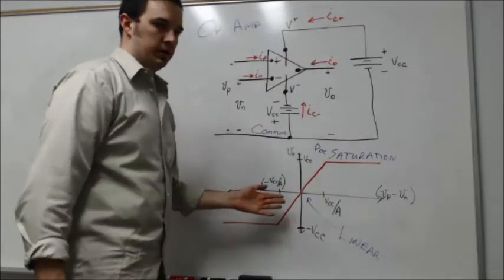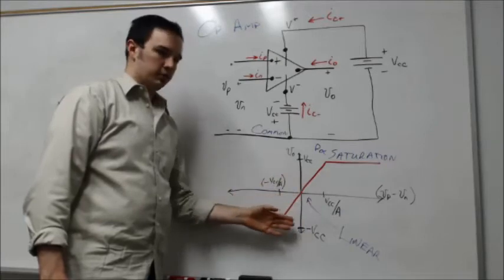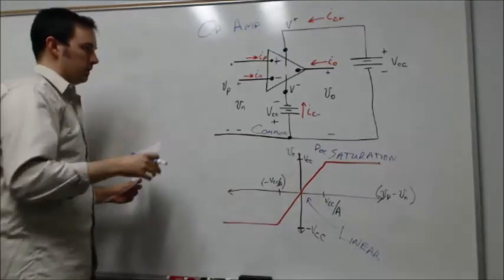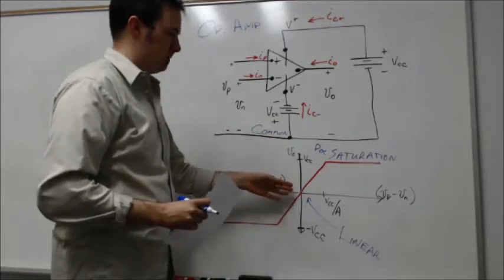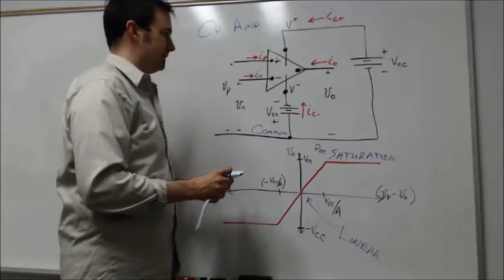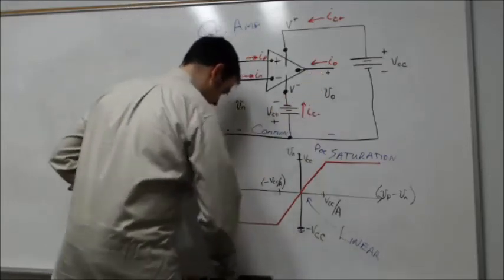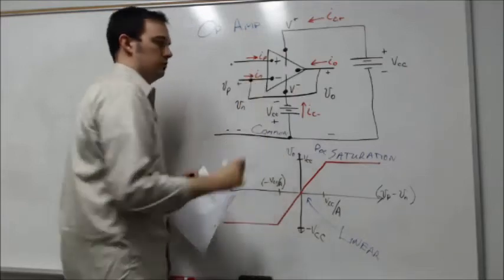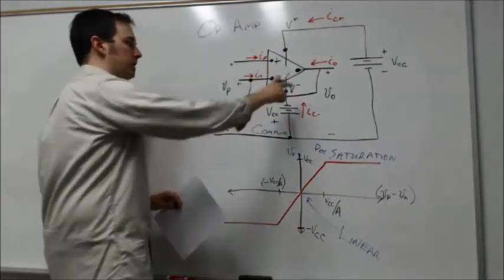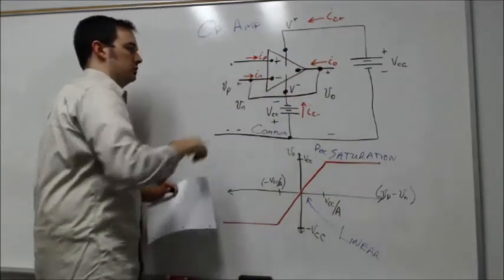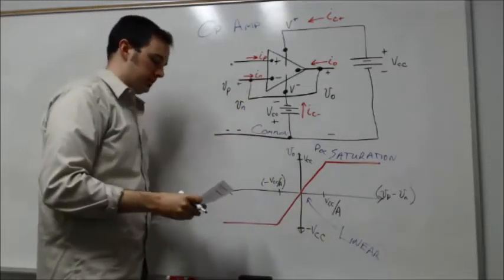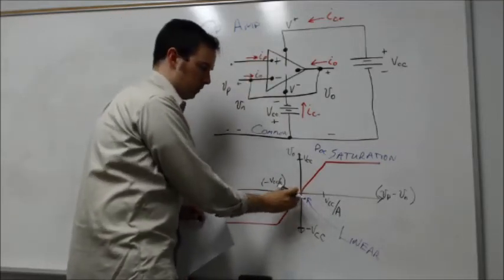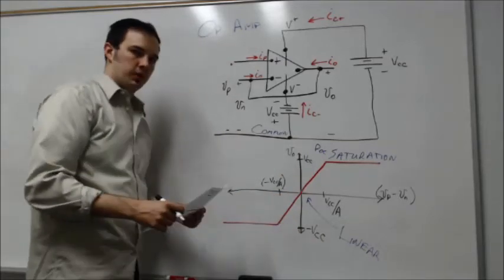We also talked about how in most circuits, especially what we're going to look at, we're always working under the assumption that we're working in the linear region. How did we come up with saying our circuits would be able to do that? We said that in order to keep the op-amp operating in the linear region, we need to have the so-called negative feedback loop. That loop is where we tie the output back over to my inverting input. That results in feedback from the output node back into my inverting input on the minus side, and that will allow this difference to remain a very small quantity, which means we remain closer to the origin of this curve.